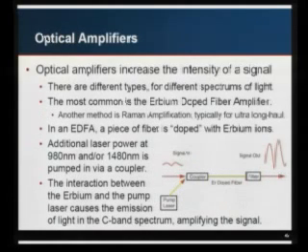The other optical component that is important is the amplifiers. Amplifiers basically just increase the intensity of a signal, just like any other amplifier. It's a volume control, basically. There are different types of amplifiers for different spectrums of light, but the one that most people are concerned with is called the erbium-doped fiber amplifier, or the EDFA.